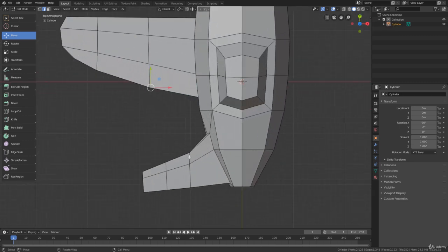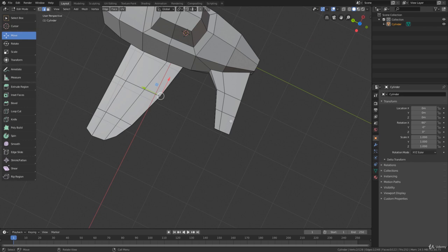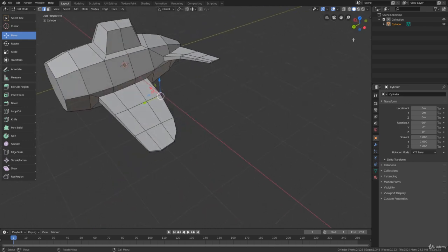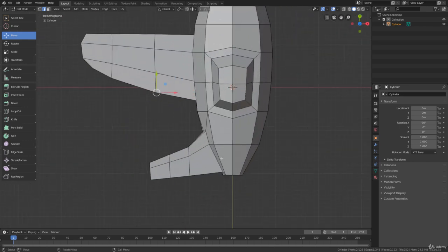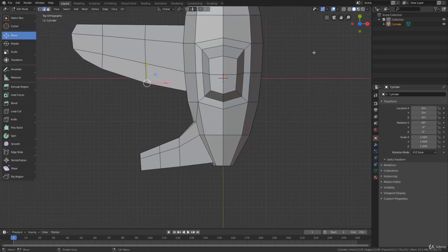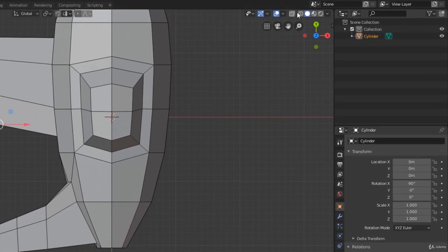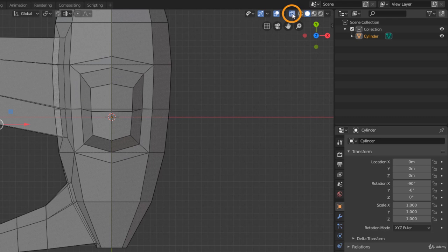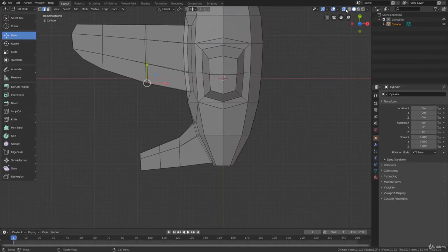But so that I can make sure that, looking from the top view, I select both vertices, the one from the top and the one that is below, back there, I need to activate the transparent mode, the X-ray mode, by clicking on this button over here, okay? When this button is selected, whenever I create a selection window, everything that is inside this selection window is selected, even if it's behind the geometry that I am seeing.